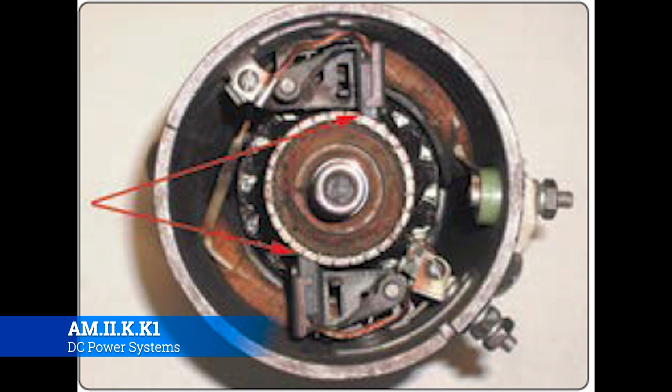So you always want to make sure that it is also secure. Whenever you pull it off, make sure that it actually is secure on the accessory gearbox mounting or engine, however it's mounted. Grab it before you start working on it. Just give it a little shake and see if there's any play. Any play could actually be a pretty significant ordeal for these DC generators.